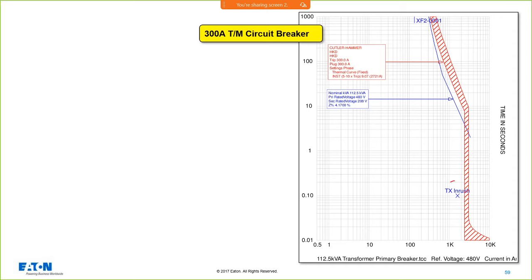There's your inrush. You don't want this breaker to trip on instantaneous.